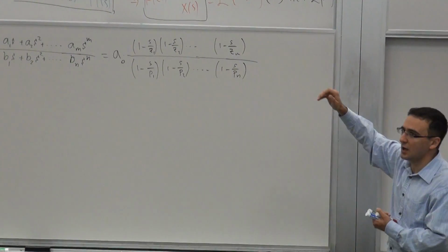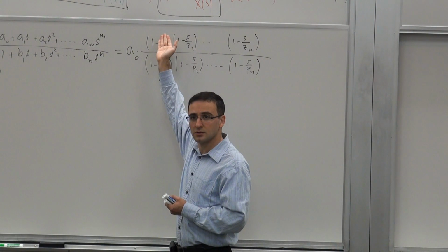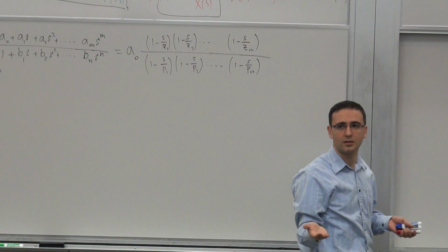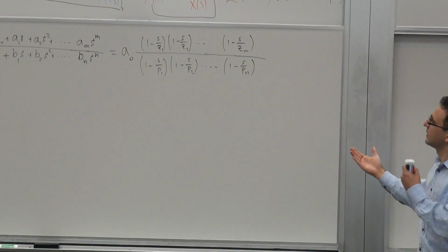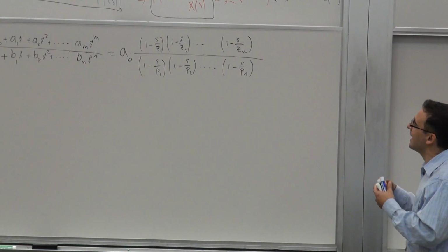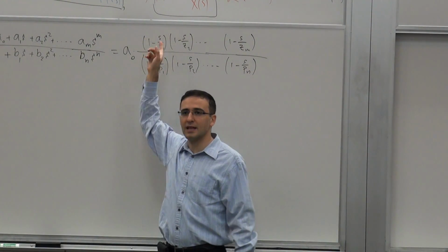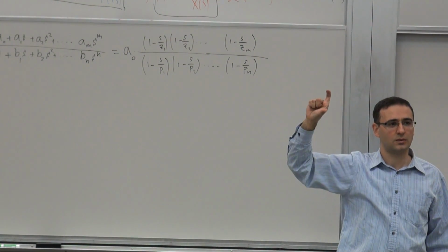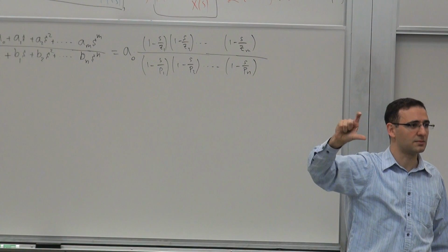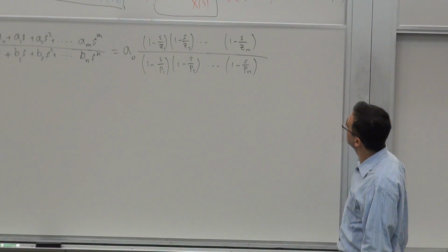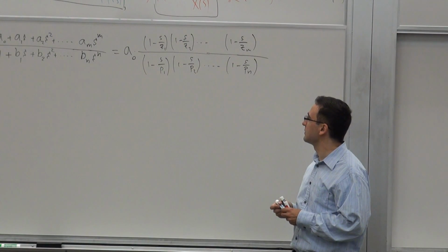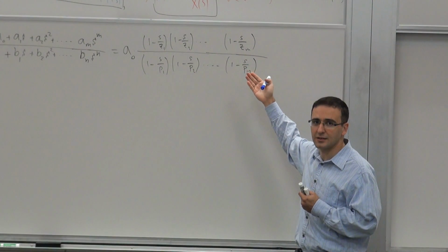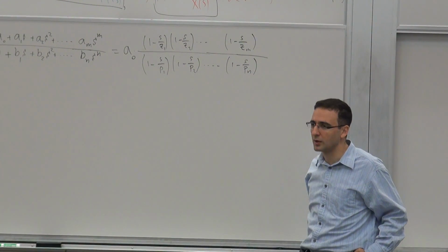Now, the roots of the numerator are called the zeros, as you know, and the roots of the denominator are called the poles. And they are in general complex quantities. So they can have a broad range of values. Since these coefficients are real, if they are complex, they always come in complex conjugate pairs, where they have the same real part and imaginary parts of opposite polarity and the same magnitude. So that's the general form of writing a transfer function. That's not the unique decomposition or factorization. There are different ways to factorize this, and I'll show you one more example that would be useful.